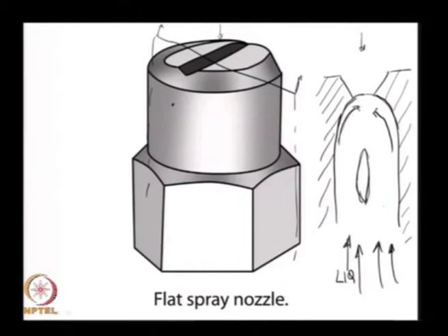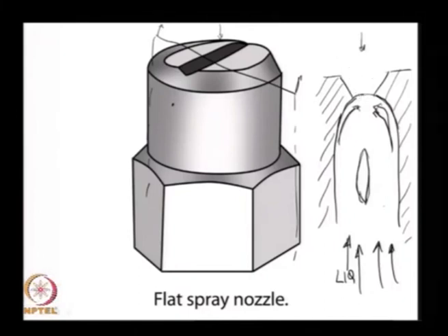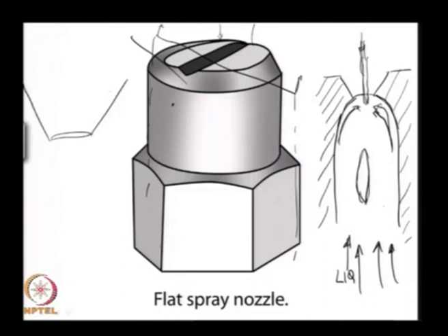So, these two liquid jets converging near the cat's eye orifice essentially cause this liquid to be spread into a thin film, and that thin film is now going to break up and create a fan spray in this direction. So, in the other plane, if this is my cat's eye, I end up creating a fan spray.